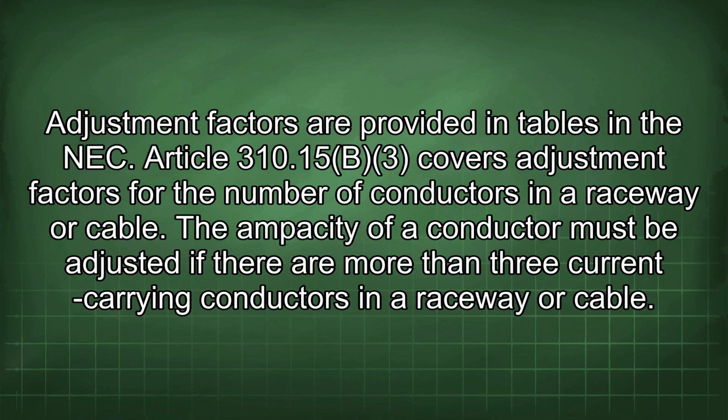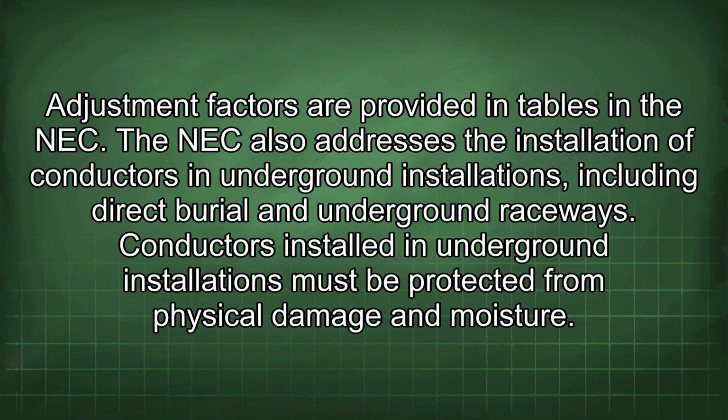Article 310.15(B)(3) covers adjustment factors for the number of conductors in a raceway or cable. The ampacity of a conductor must be adjusted if there are more than 3 current-carrying conductors in a raceway or cable. Adjustment factors are provided in tables in the NEC.